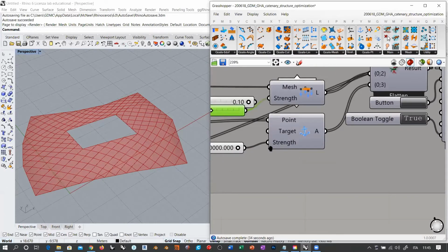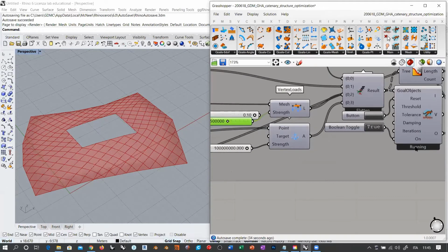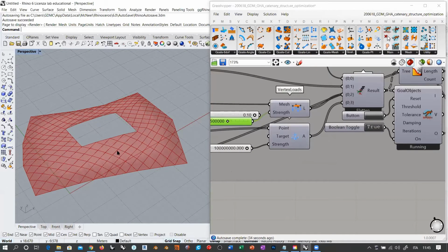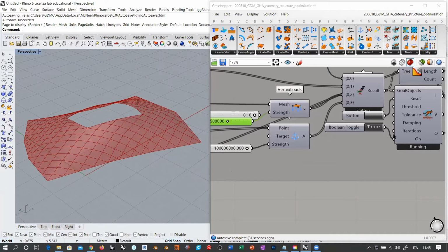Eventually, if we go here, we should start to see that this thing is starting to move. You see, it's running, but see how slow. Okay, so yes, you have a simulation running right now. It's actually pretty fast if compared to what happens with a real structure, with a real consistent amount of elements. But nevertheless, before this gets to a converged status, it's going to take a while, because the final oscillation, the final vibration around the equilibrium status, is going to be very, very slow.